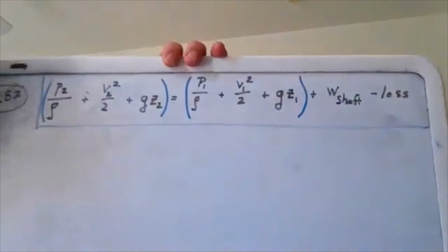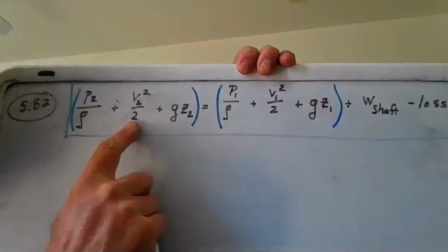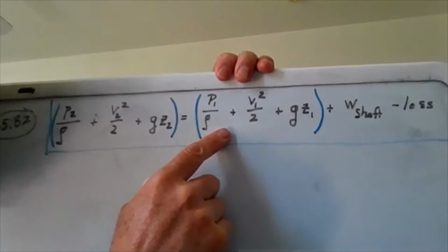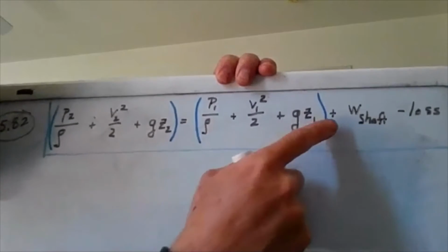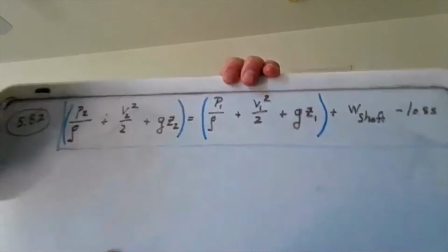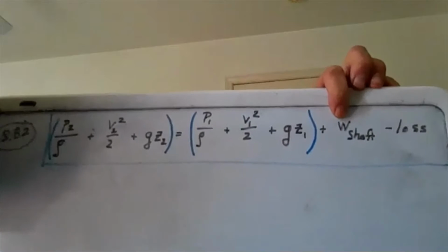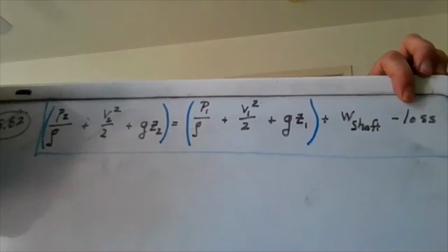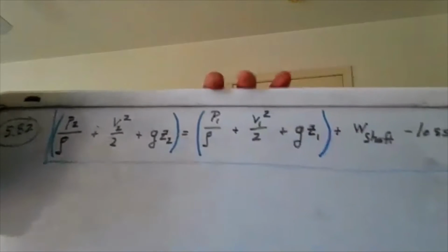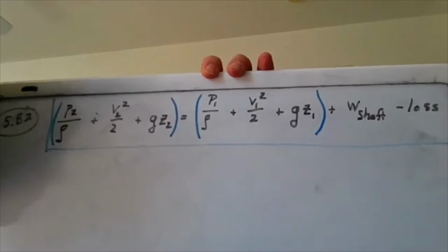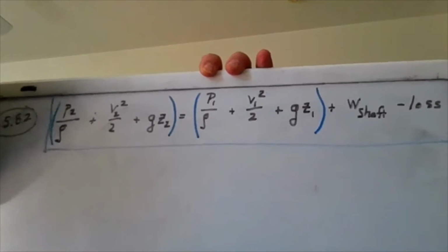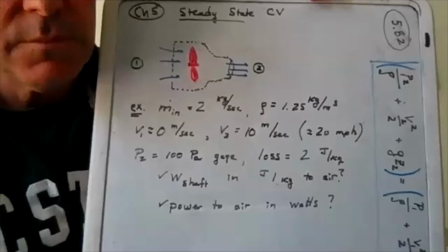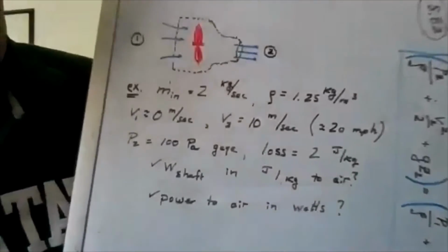And in short, we could describe this by saying, look, the energy the fluid has coming out is equal to the mechanical energy the fluid has in, plus any energy added by, say, a pump's blades or a fan's blades, etc., minus any sort of loss. Okay, and that is a very powerful equation. We'll ask you to do some practice with that and understand what's going on as far as energy. All right, let's work an example to feel how this is going.